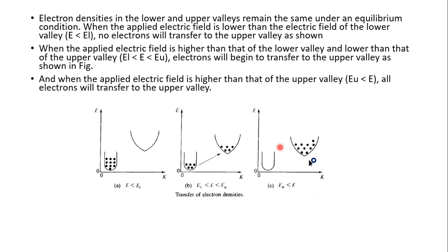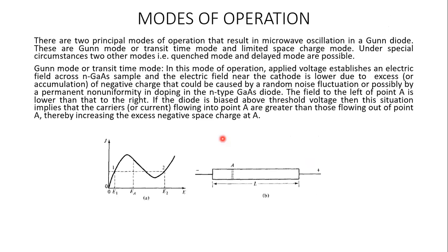And this particular property is used to make a negative resistance device, where the applied field is larger, but if it increases, the current decreases. Now, with the help of this specific property of the Gunn material, gallium arsenide, this particular behavior is used for making use of gallium arsenide as an oscillator, or in the design of an oscillator, you can say.